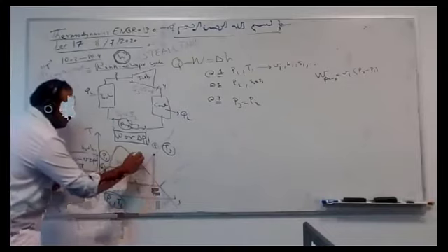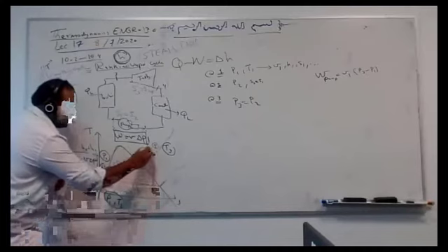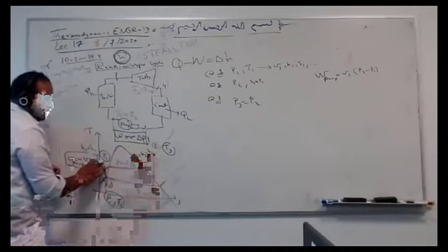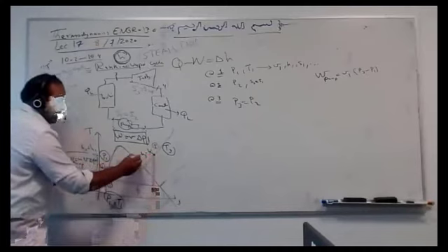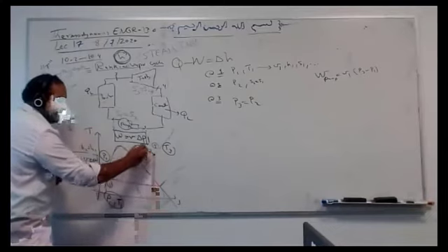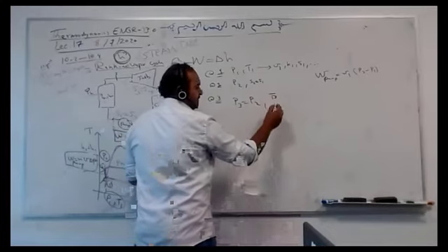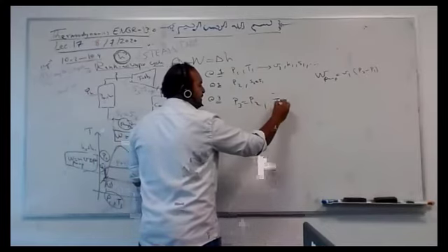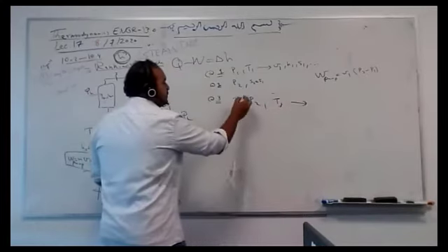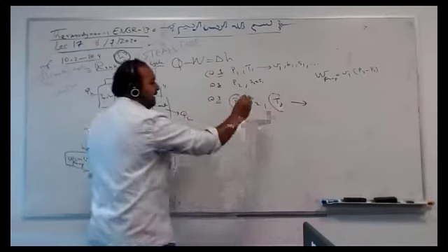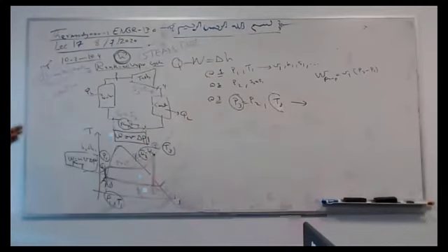So Q high, which is H3 minus H2. You have H2. From H2 and Q2, you can get to H3, which means you have either T3 or H3. But now I give you, for example, T3. If we have two independent intensive properties, you can get everything.